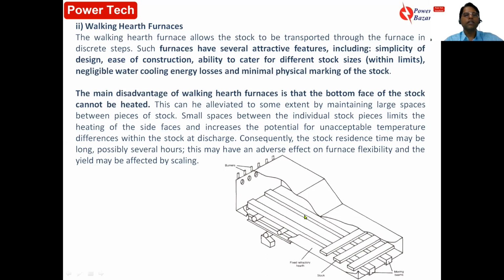The hearth in this case works to move the materials so that they are continuously heated up, and after the soaking zone they get discharged. Now these furnaces have several attractive features including simplicity of design, ease of construction, availability to cater to different types of stock size, negligible water cooling loss, and minimum physical marking of the stock.